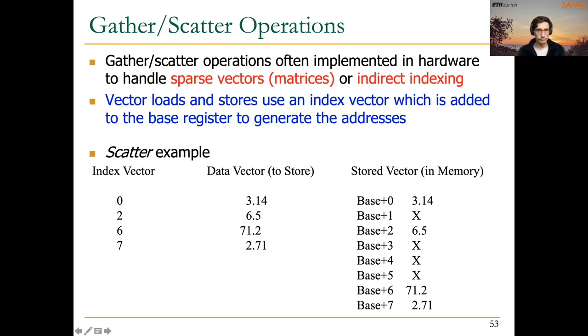So now we know how to operate using vector and SIMD processors in the regular manner when the computation is completely regular. But now we also know how to optimize the access to memory using banked memories. We know how to deal with incomplete vectors when we don't need to use all the lanes, all the registers in a vector register. We can change the vector length.